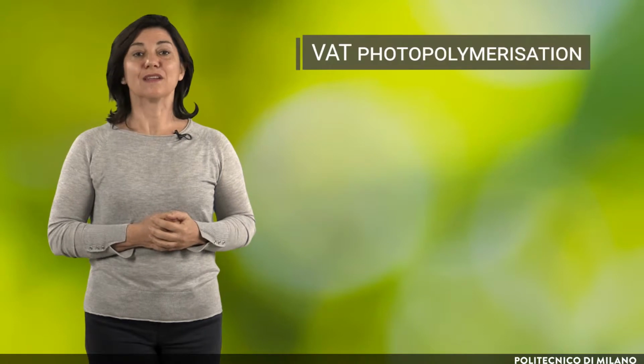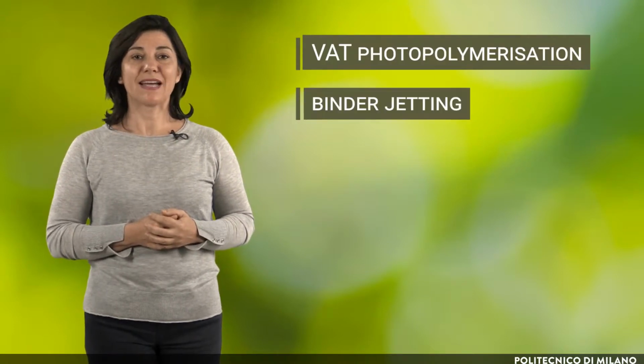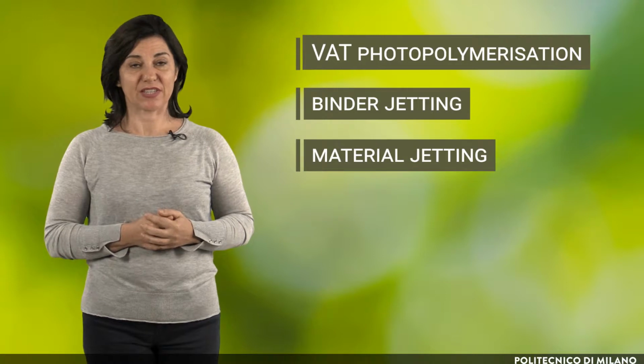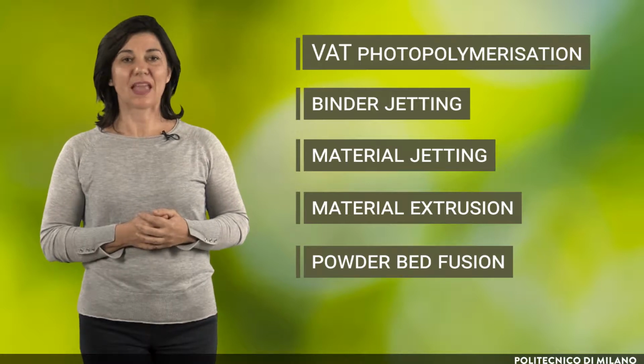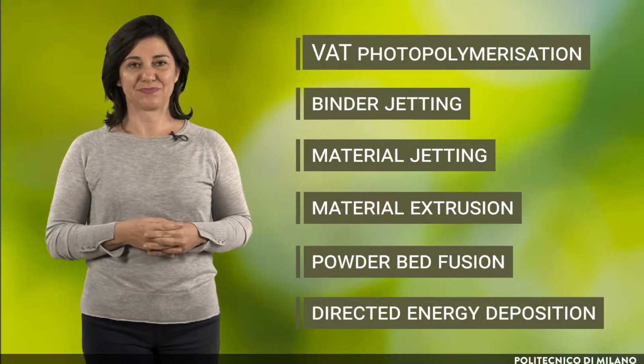There are multiple processes developed for additive manufacturing, which vary in material, process, final shape, and surface finish. According to European standard and ISO 17296 Part 2, these are grouped into 6 basic categories based on material and machine technology used: VAT photopolymerization, binder jetting, material jetting, material extrusion, powder bed fusion, and directed energy deposition.